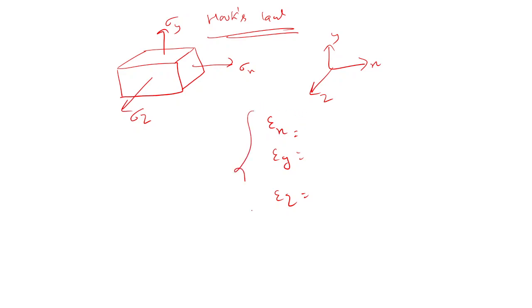is it clear what I'm doing? Yes. So here strain will come due to all these stresses, right? Yes, sir. So first of all, direct stress will come. It would be sigma x by E. Now the effect of this will come.